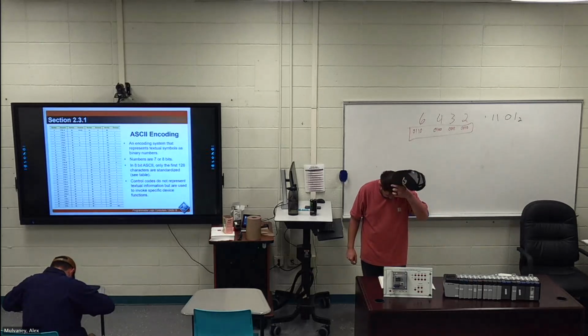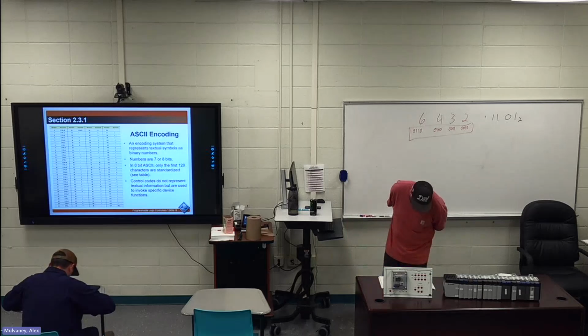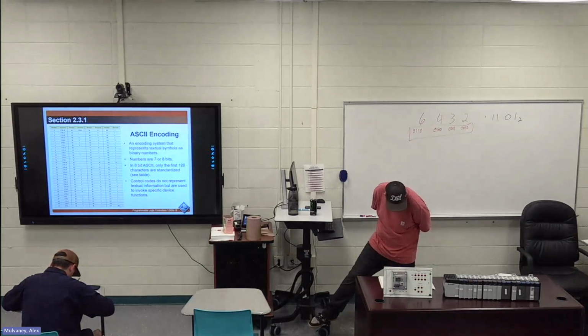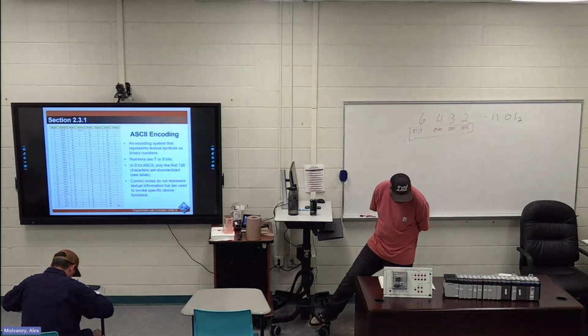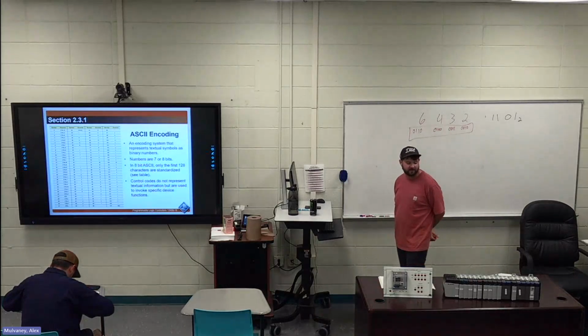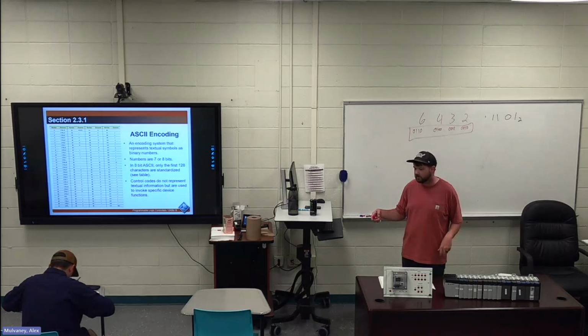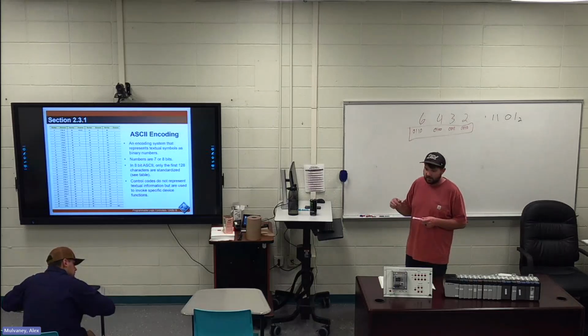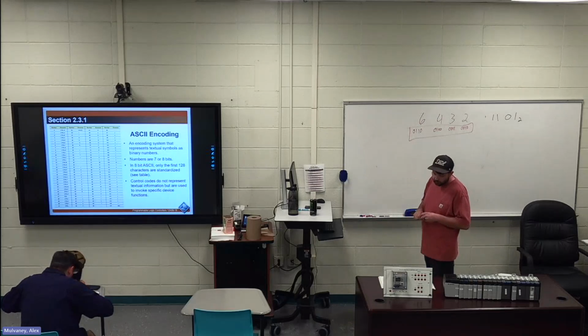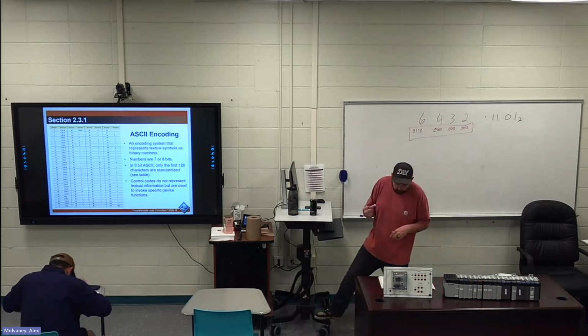Gray code. Gray code is a modified binary code used by rotational or linear motion encoders to convert motion positions to a digital value. So that's what I was talking about. These encoders look like a little bitty motor. They have a lot of wires coming off of them, and the wires have little magnets on the inside, and that's what turns them on and off. And that's how you can create rotational code, which is Gray code, from an encoder.